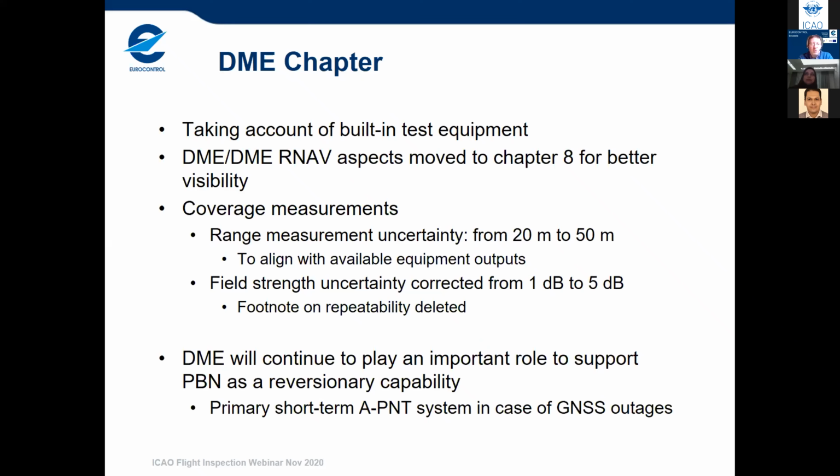And so we said that actually you should make a best effort to get to 5 dB accuracy, and that is really taking a realistic look at what you can achieve in terms of AGC (automatic gain calibration) and antenna pattern calibration. And once you do take a realistic look at these, then of course getting the 5 dB is already quite ambitious accuracy.